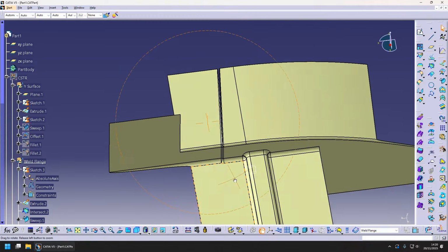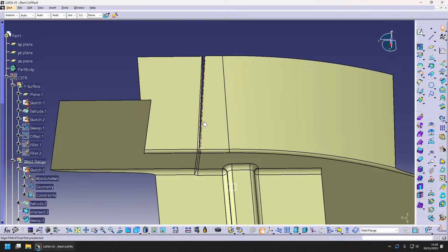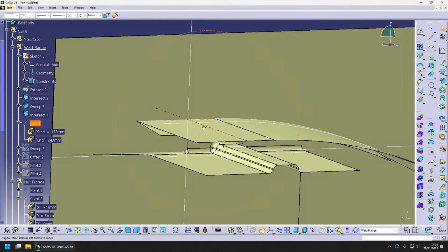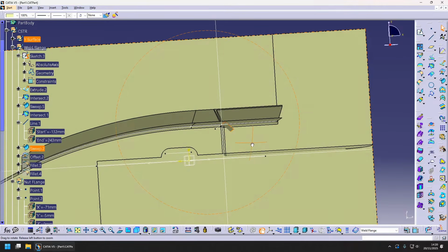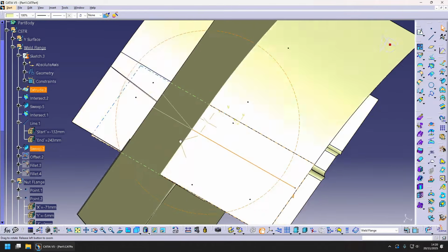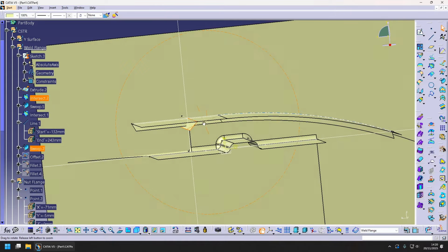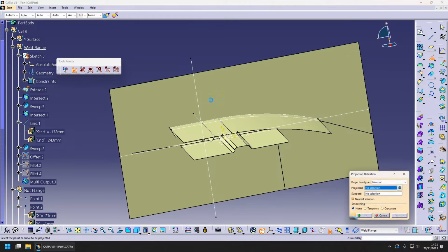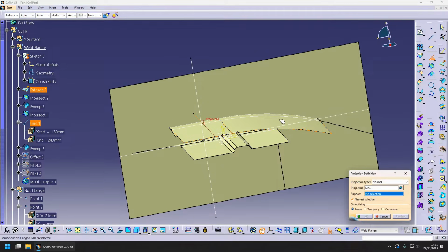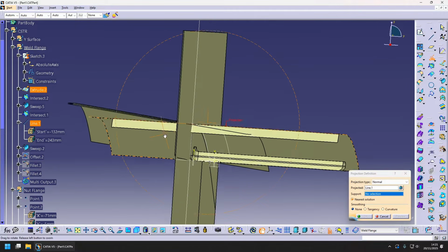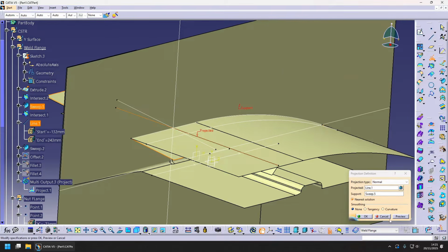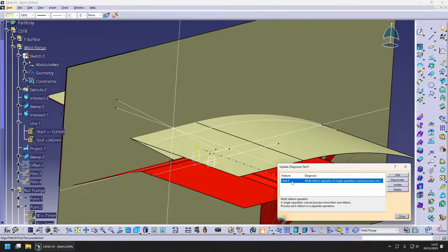If you hide the construction set, see, this surface here is angled, but we have a problem. The step doesn't look too good. That's probably because when you sweep this line, that's how it intersects the new angled surface, and that's a problem. So we go back to the line, select insert mode to replace the line. Okay, now we project the line to this new angled surface. I just need to find it. Yeah, this one, the sweep. And now the line will be projected on that surface.